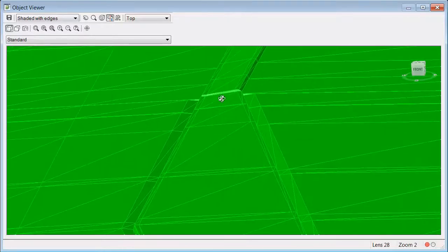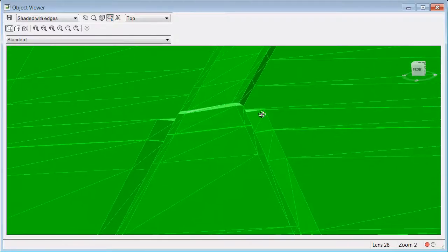Let's pan this down a little further and I'll zoom in. Here I have an elevational issue. This is the transition from my Type F curb to the Type D curb. The problem I'm having here is the Type F curb includes a 2% downward gutter slope, whereas the Type D curb does not. We can see the lane travels upward, continues here at 2%.